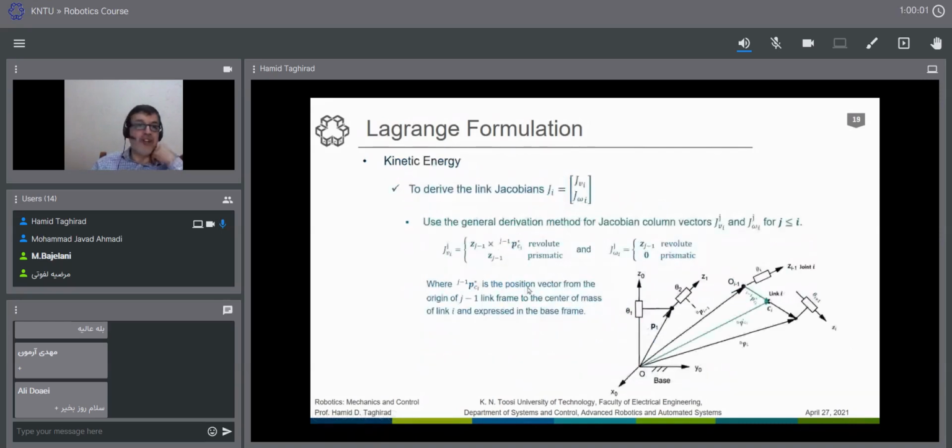Here is the final treatment, and the figure that I said. First, consider that we had a link, and we had some screw axis or a Z axis. There is no difference: if you are happy or clear with the screw, you can go with the screw representation because they are the same thing, or you can go with the Z axis and then the Denavit-Hartenberg representation. All these formulations are quite the same.